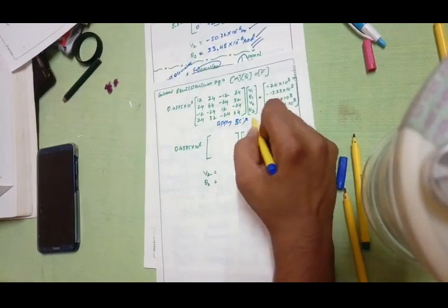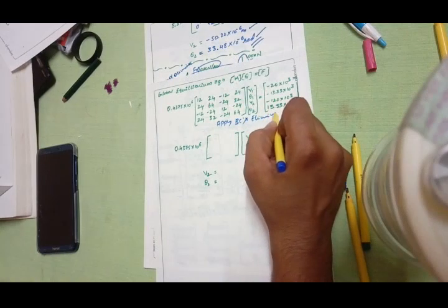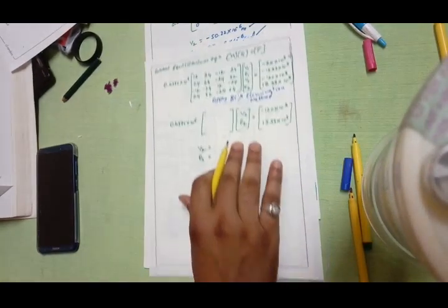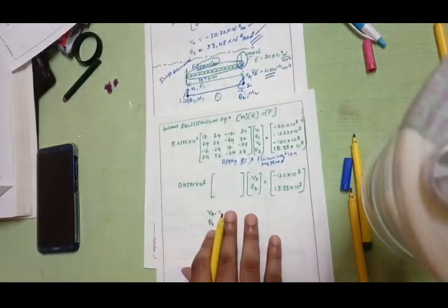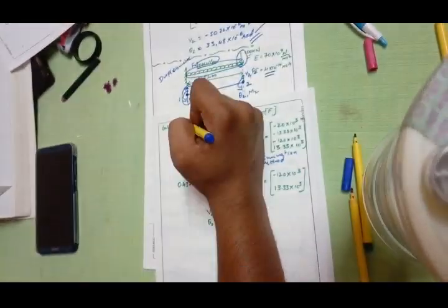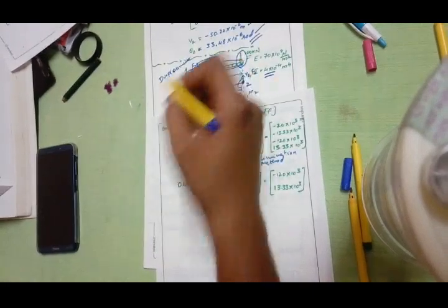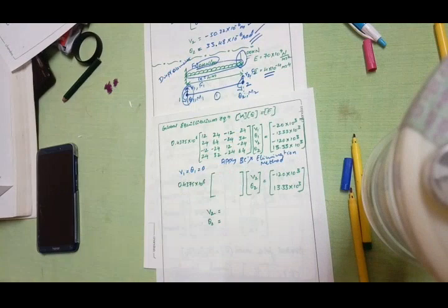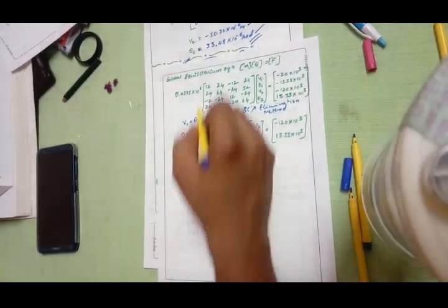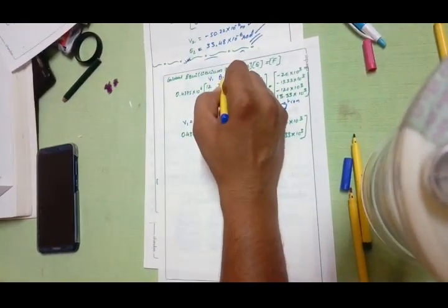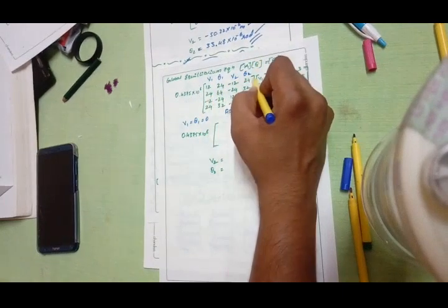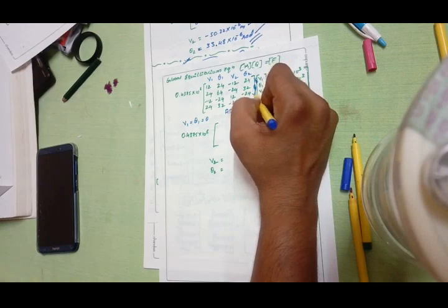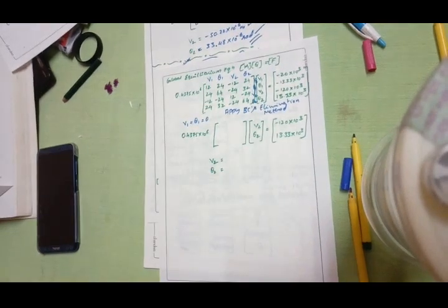Generally that is the elimination method, the method we are going to use. Now, by looking at the problem, you can see that since one end is completely fixed, that is node number 1 is completely fixed, displacements at node number 1, that is V1 theta 1, are assumed as 0. So what you need to do is very simple: V1 theta 1 V2 theta 2. I'm writing the degrees of freedom. Similarly, V1 theta 1 V2 theta 2 are the degrees of freedom.